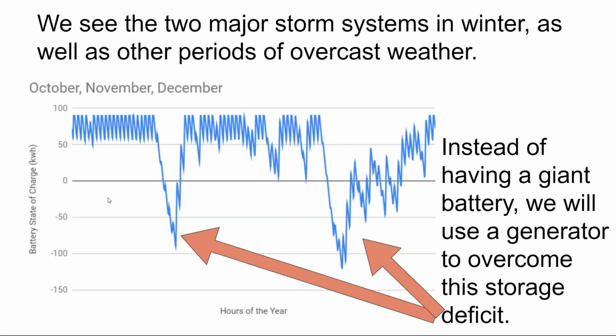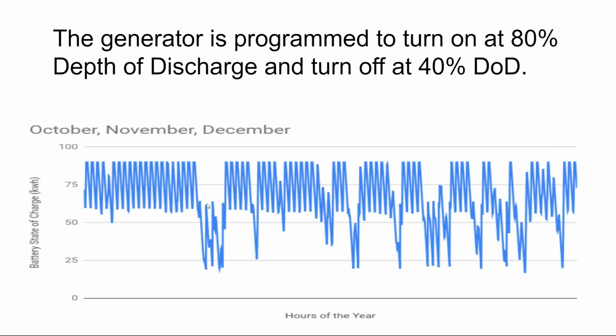So let's say you were throwing a New Year's Eve party and we're cranking the hot tub and using the oven and just having 100 people over, a higher end system would let you add the two power capacities together, the generator plus the battery. A lower end system, you would just be using the generator to either charge the battery or bypass the system altogether, such as if there was a component failure, to just run off the generator until that was fixed. So that starts to get into technical discussion.